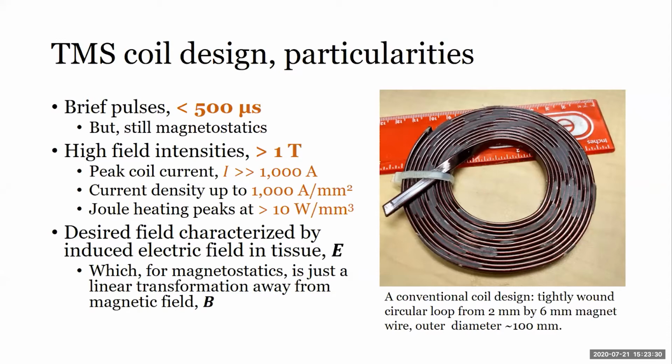So the basically only suitable material for pulses like that is copper, which has nice heat capacity, so that it heats limitedly during the pulse, and then cooling between pulses either by having some thermal mass to keep things cool, or even with active cooling. So that is the particular problem, but some of the tools are applicable to other problems too.